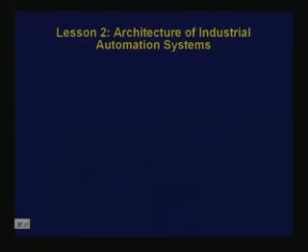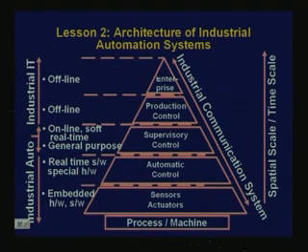And then in the next lesson we took a look at the architecture of industrial automation systems, and we introduced the automation pyramid and the levels of automation. So, we talked about level 0 of sensors and actuators, then level 1 of automatic control of various protections, alarms, then supervisory control, process monitoring, set point optimization, then production control, scheduling, maintenance management, inventory, then finally enterprise control, where we basically have finance, business, HRD, marketing.